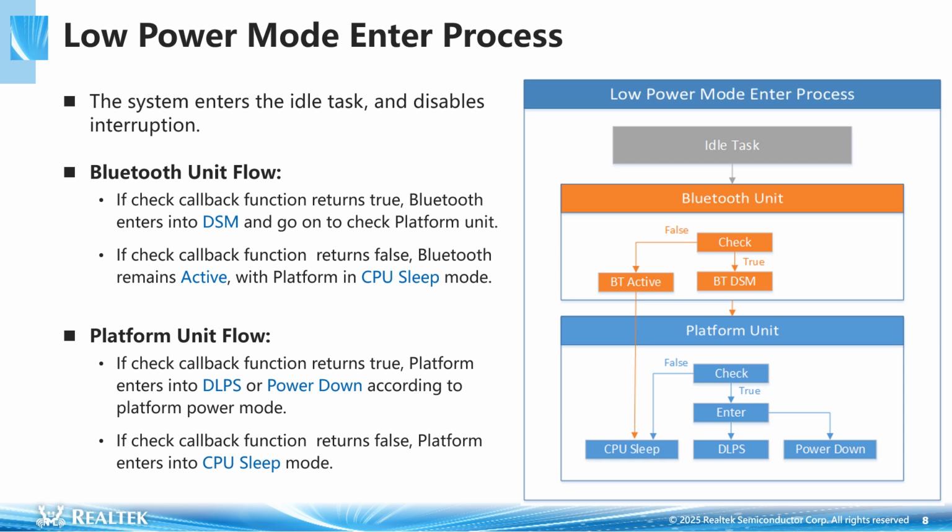In platform unit flow, if the check callback function returns true, the platform unit will enter DLPS or power down mode, depending on the platform power mode. If the check callback function returns false, the platform unit will enter CPU sleep mode.